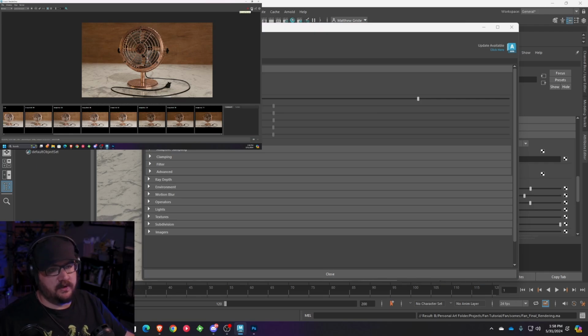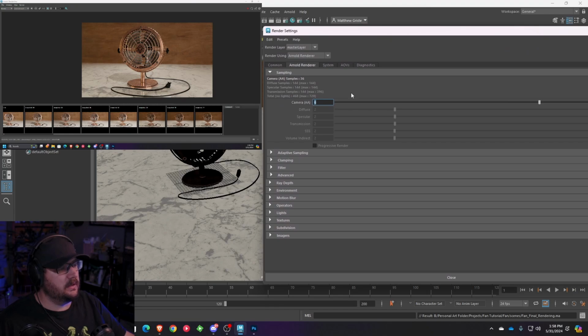I'm going to render one more time. And just so you can see what I changed, because I just saw it's in the way again. Right here, under Arnold render, you're changing your camera settings, your camera. So we're going to render that. That should clear up a lot of the noise.